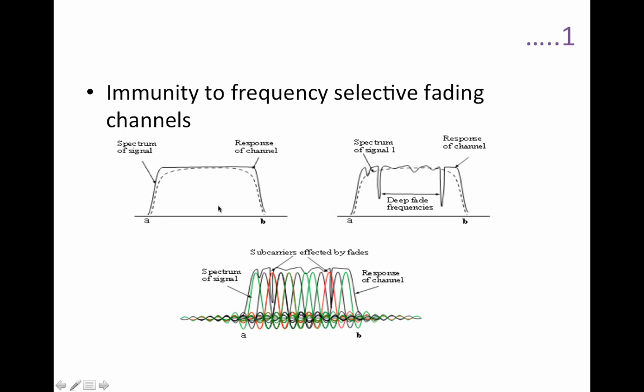If the transmitted signal has a greater bandwidth than the range over which the channel's frequency response has constant gain and linear phase, then it undergoes frequency selective fading. If the delay spread is more than one symbol, then the channel undergoes frequency selective fading.